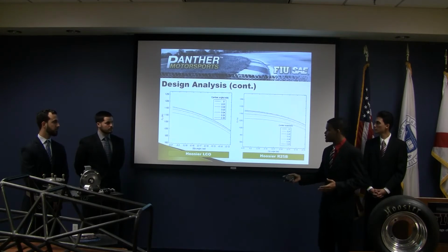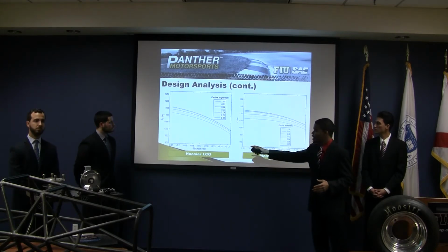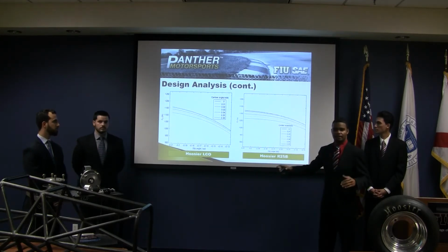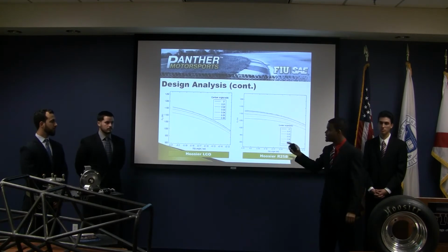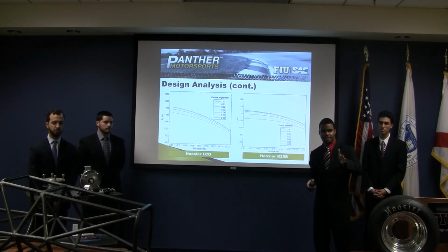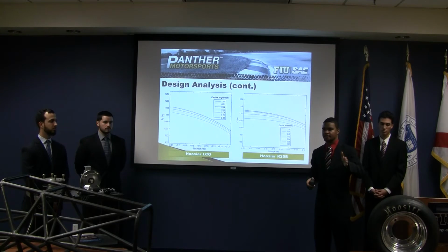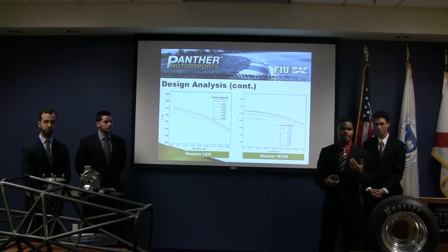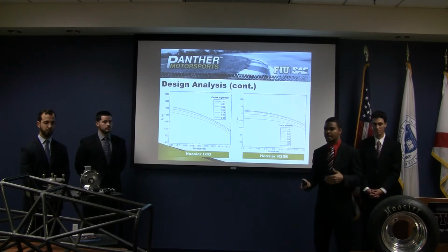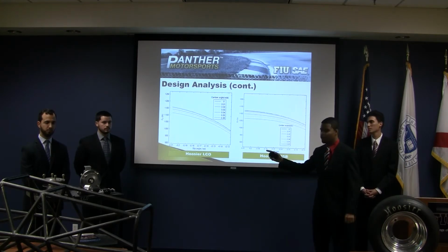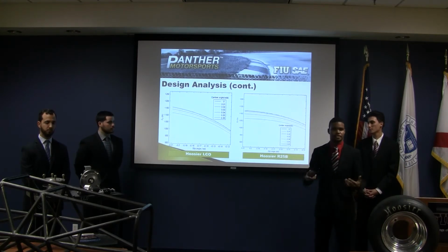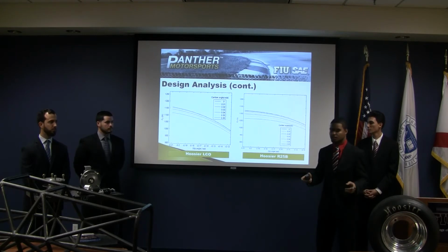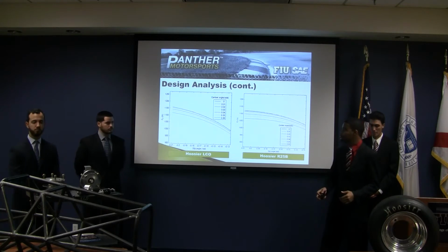But the LCO tire compound, as you see on the left, generates a maximum amount of lateral force, turning force, and is less susceptible to changes in the camber angle, which is the tilt angle of the tire. So even though this tire is less drivable, that drivability can be mitigated through driver training and driver seat time. But this performance cannot be mitigated unless you use an expensive aero package. Thus, we chose the Hoosier LCO tire compound for our vehicle.